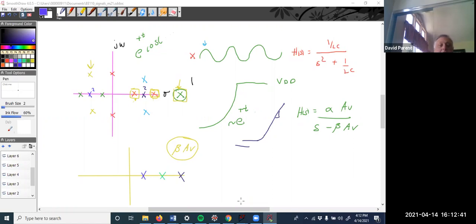So Corinne, your question: not necessarily, you don't always need a summer. Now there are some rules of thumb. If it's a high pass filter and B naught is 1, you can make it so that you don't need a gain stage.